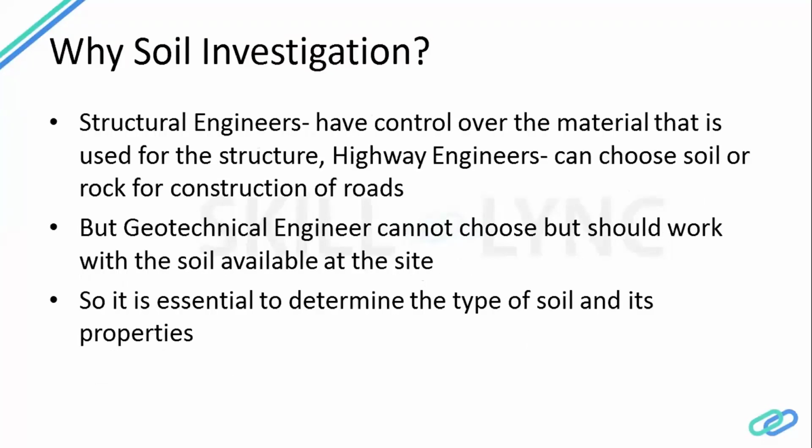So what is the actual requirement of soil investigation? A structural engineer usually works with concrete or steel, so the material he is going to use is known to him. Also, highway engineers select rock or soil from some borrow position, so they know the properties of what will be used. But for a geotech engineer, at each site we have to use the soil available at that location. So those conditions have to be analyzed, and for that we require the soil investigation to be performed. We'll move on to the next slide.